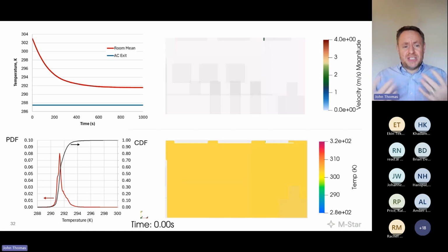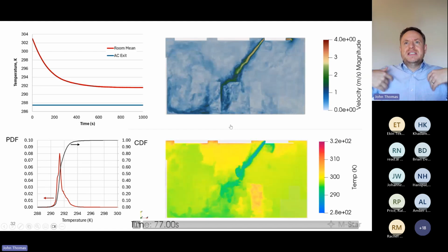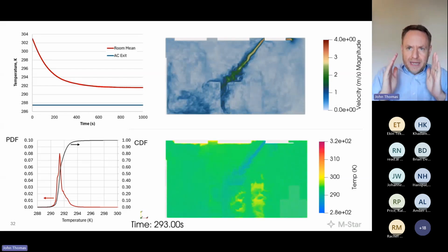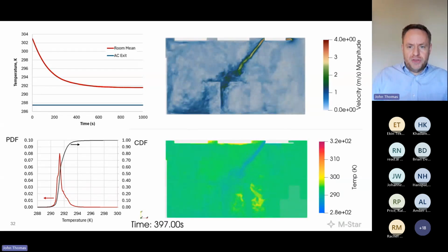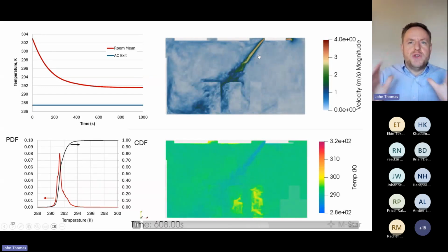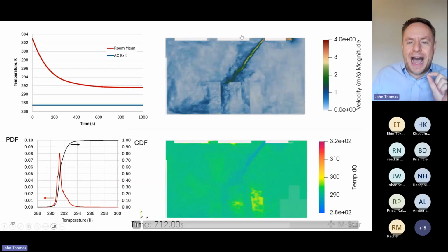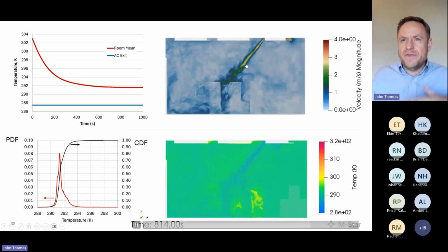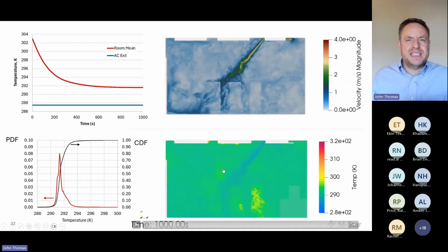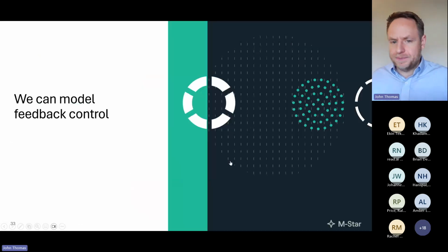But again, I'll emphasize this point. This wasn't, oh, let's predict a mean flow field and then throw a temperature solver on this. These tens of minutes and hours of long simulations are happening in tandem in a multi-physics manner that allows us to bridge the link between eddy timescales and process outcomes. So again, there's an incredible view here. We can understand how the individual eddies that arrive and decay over a fraction of a second ultimately inform the several thousand second process outcome. That's neat when you have a holistic view into process mechanics.